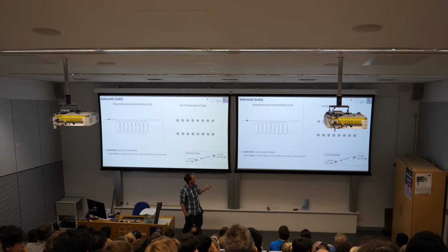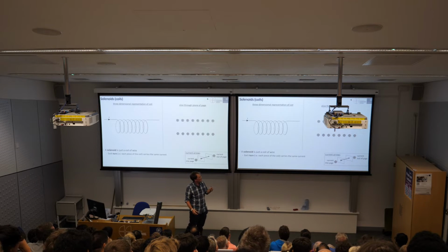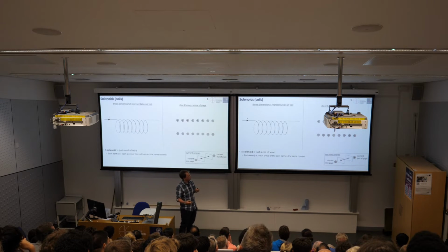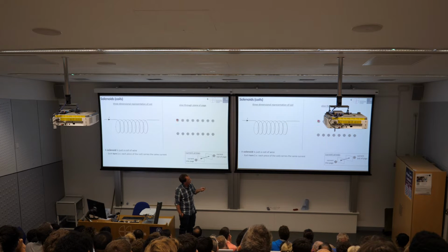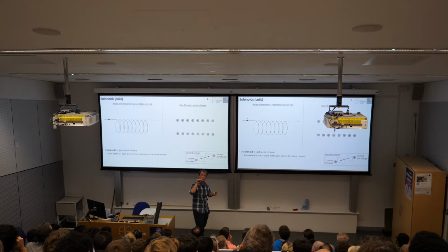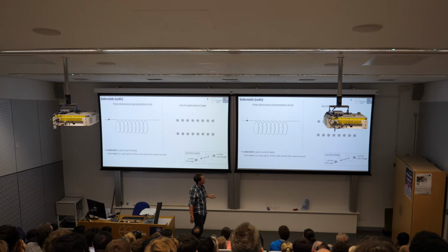And so when I have a 3D coil of wire, engineers often express these arrangements by slicing through the plane of the page. And so you often see diagrams that look like this, where each one of these represents a current carrying conductor. The dot here means the current is flowing out of the page towards you, looping out, and then coming back down through the cross. So the way you think of it is like you're looking at an arrow zooming towards you in this case, and here, an arrow zooming away from you into the page, right?